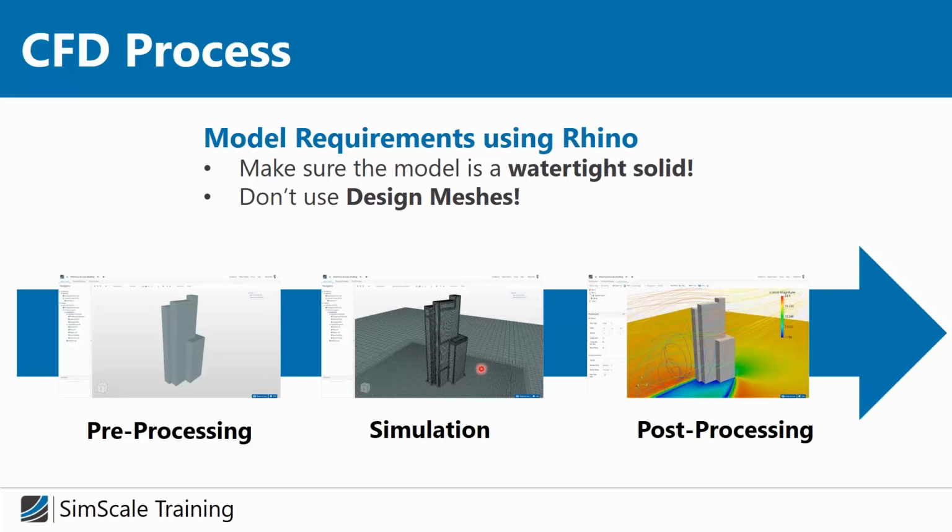But it's a different kind of mesh than you use for modeling something. It's more a visualization of the spatial discretization. Everywhere this mesh is fine, the accuracy is very high, and everywhere it's coarse, it's low, because we will only calculate velocity and pressure for the centers of these elements.